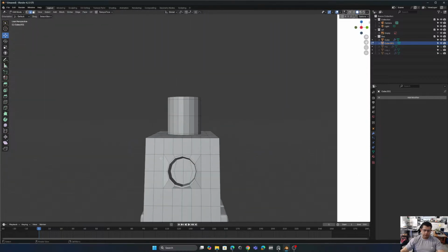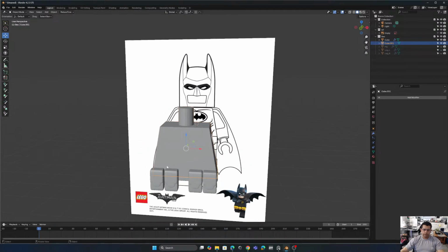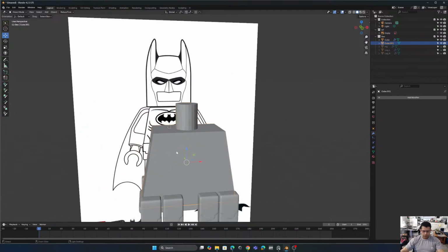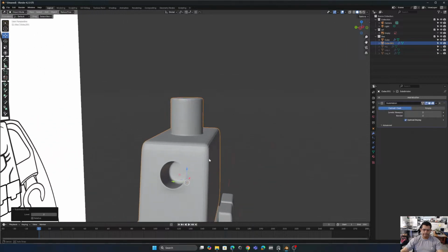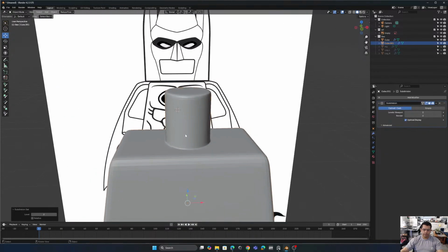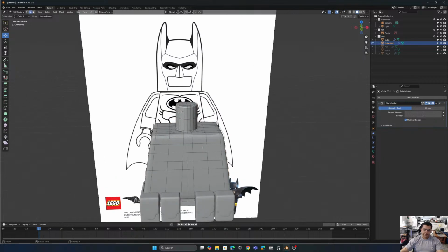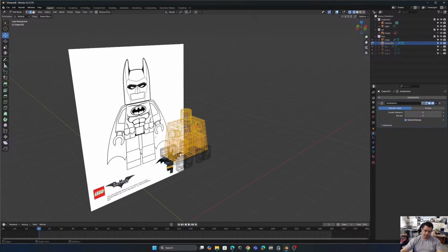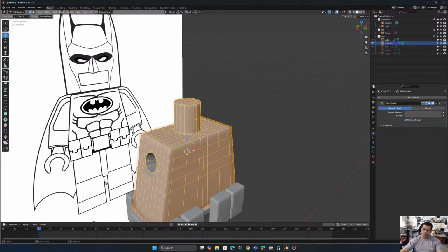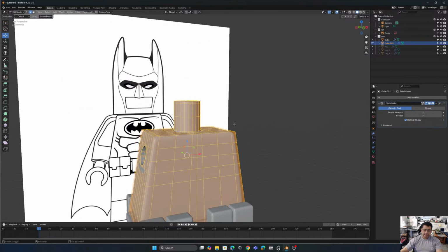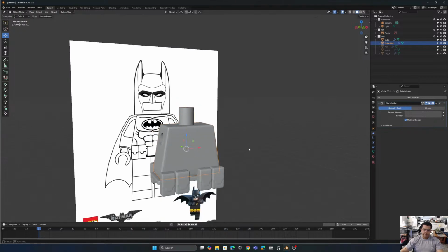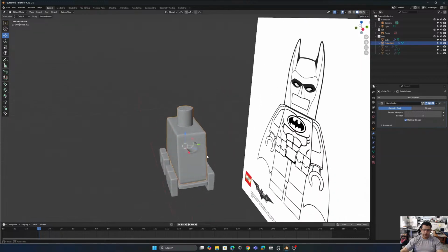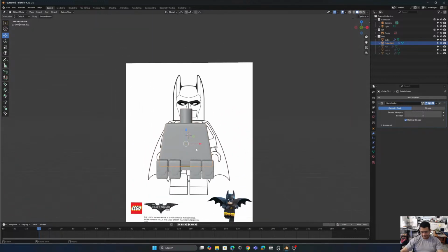Now tab to go out of the edit mode. Ctrl 2 to smooth it. And as you can see, the loops preserve the shape over here. We could press Shift Z to go to wireframe, select everything, Shift Z to get shade mode again, Shift E, and we could edit how much smoothness we want. I think something over there. Perfect. So much better. I like it until now.